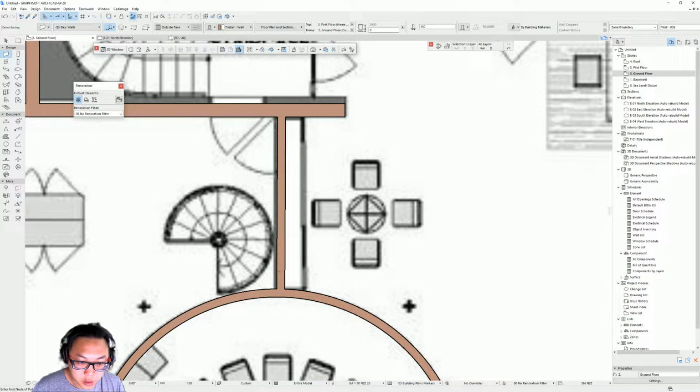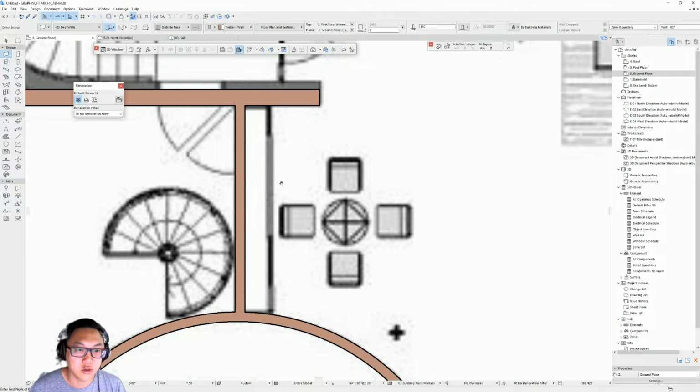Yeah, you have to be careful. You can see here it wasn't straight, so I'm just gonna delete that, Control Z. Make sure that you follow the guideline. You can go over it sometimes. If you go to the edge here, as you can see, there's the guideline and there's the middle point, and because they don't line up, you might click in the wrong place. So you can just go further, make sure that you follow the guideline, just double click and Control to get the scissors and cut the part that you don't need.